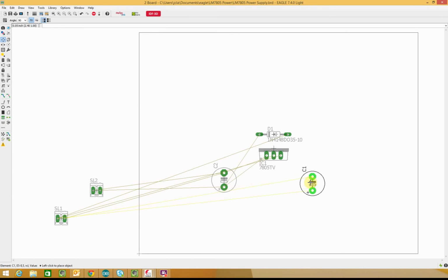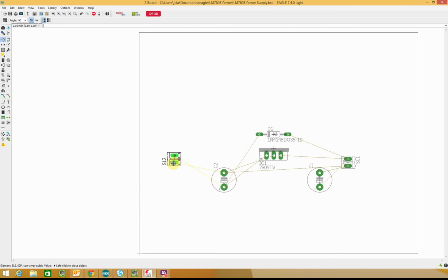The yellow wires you can see here are the connections that we need to route when you start to route the design. If we go over here and click, we update the net a little bit so that these lines show the shortest connection, the most direct route to the next pin that it needs to connect to. You can see here that we have these two lines crossing here. So if we just take this and rotate, they're not crossing anymore, so it makes it easier to route it.